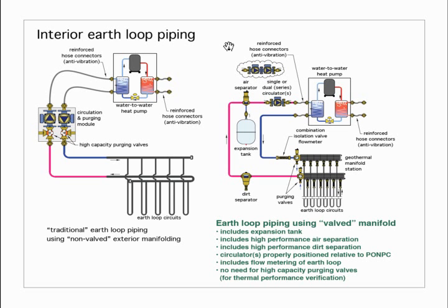One is you see an expansion tank. I'm a firm believer that earth loops should have expansion tanks. That fluid does heat and cool. It does expand and contract, and so does the piping. And without an expansion tank, you can have some fairly wide pressure fluctuations in that loop. Where the problem tends to come up is in the cooling mode, where the pipe actually expands faster than the fluid. The pressure in the system can drop, and I have seen it drop to the point where it will actually cause a cavitation in the pump. By having an expansion tank in there, you can stabilize that pressure.